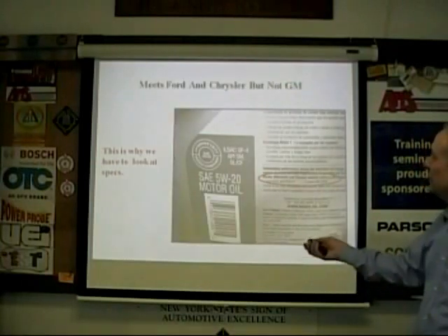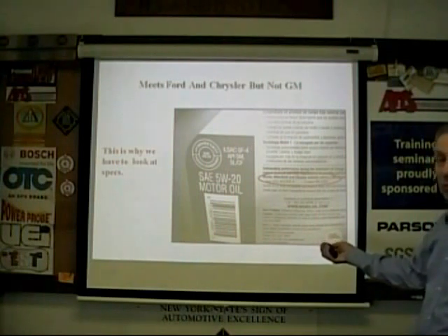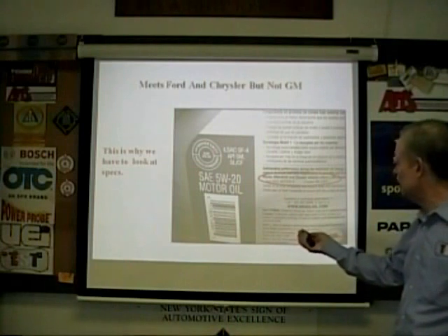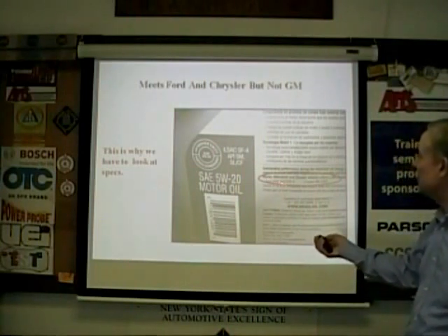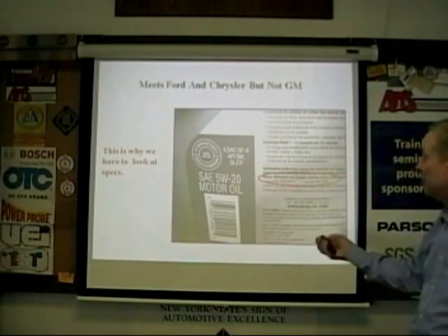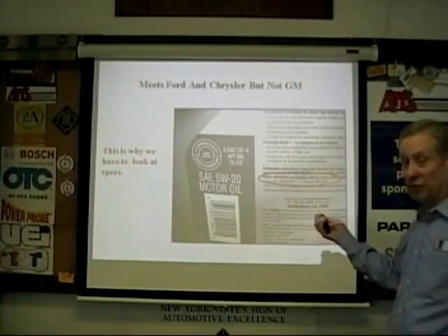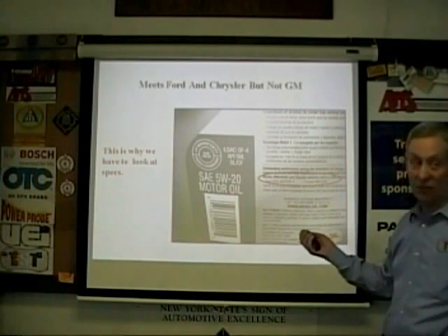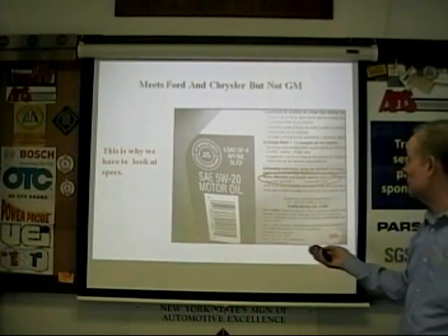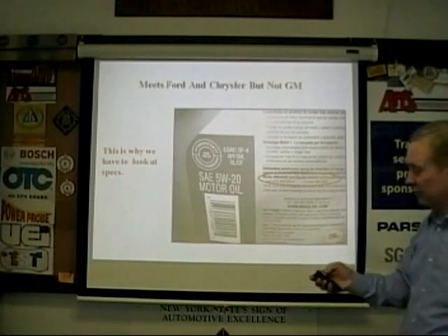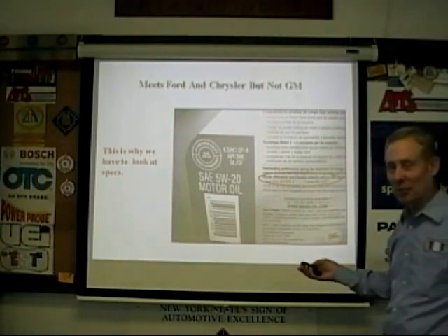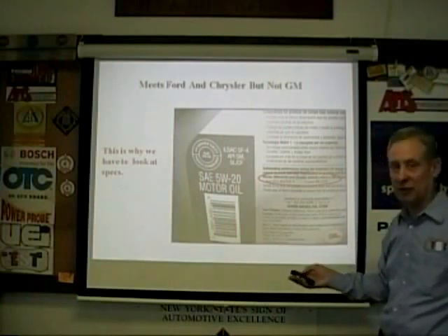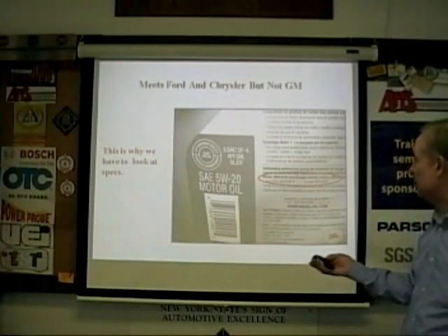Alright, this oil here is a 5W-20, but it only meets two manufacturer specs. This Ford spec, and by the way, manufacturers have different specs. And this says Ford WSS M2C930A. It has to be that spec for whatever Ford you have. Same with Chrysler, Chrysler MS6395. There are multiple specs manufacturers have. As a rule, and we all know rules are made to be broken, the newer spec is backwards compatible, it covers the older spec, but that's not always 100% true.